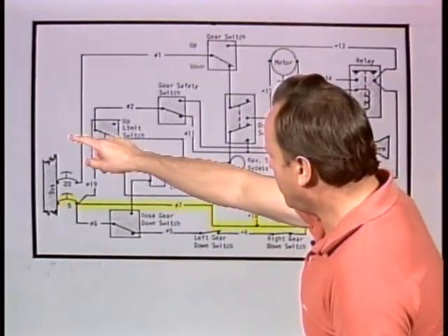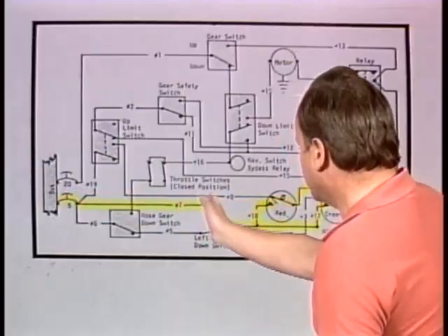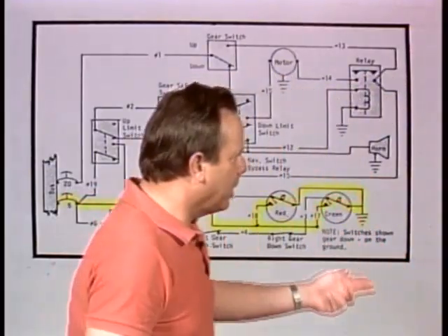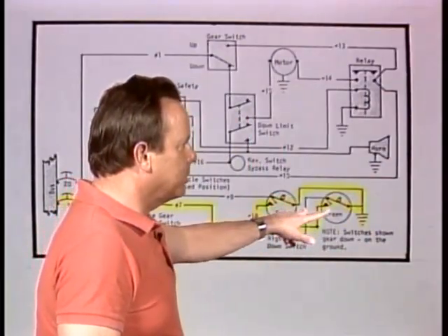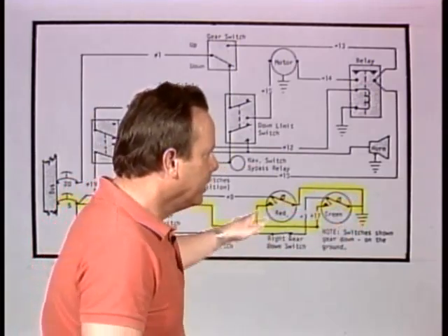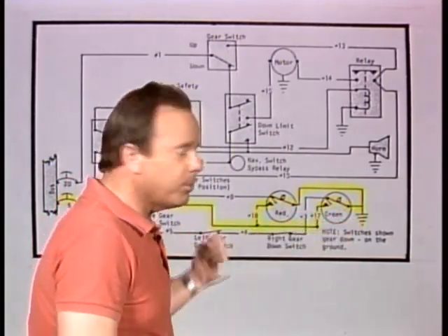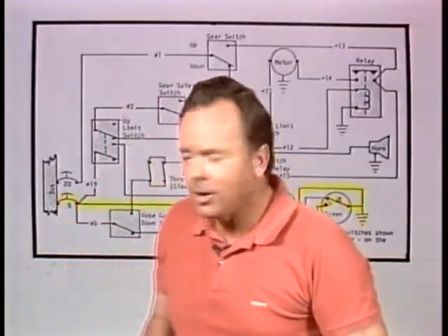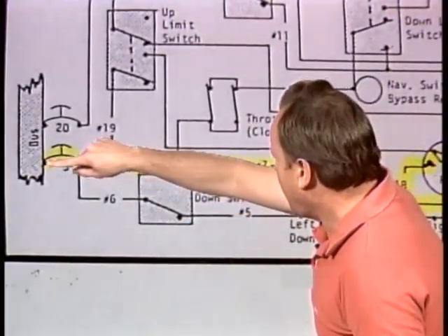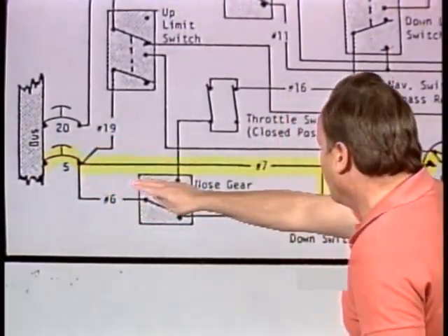First of all, we have the bus on the left-hand side. Wire 7 will go around here. We'll trace this in more detail in just a second. And then you get over here on the right-hand side, a couple push-to-test switches and lights, and then finally a ground. So what we need to do is complete the circuit from the power source to the ground. All right, let's start over at the power source. And here we have a bus with a 5-amp circuit breaker and then wire 7.